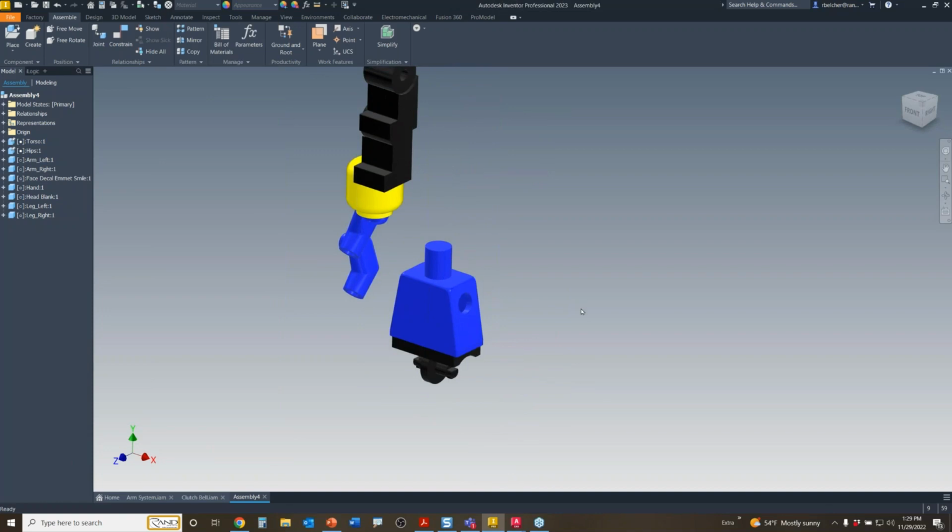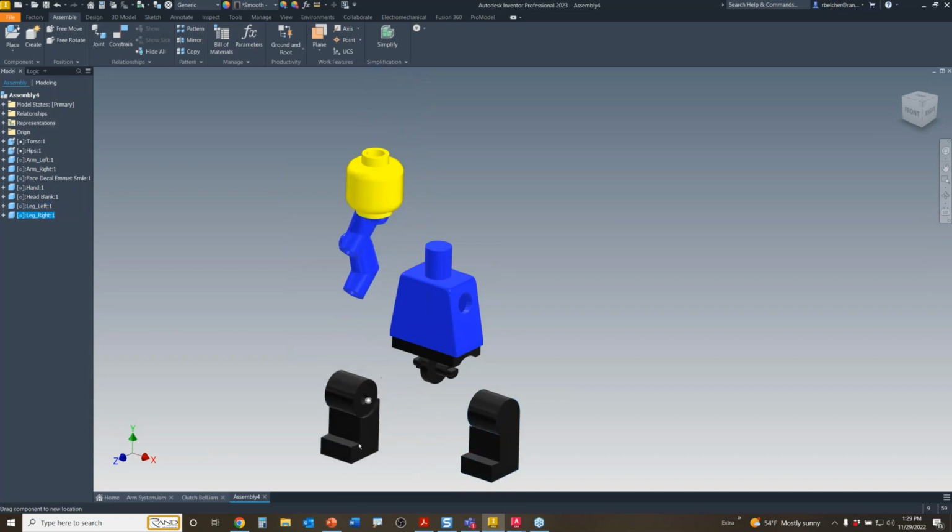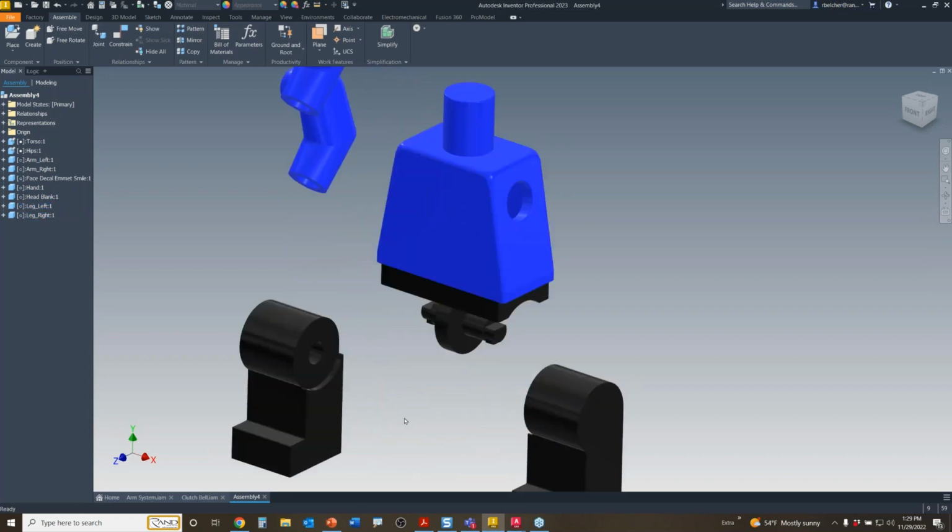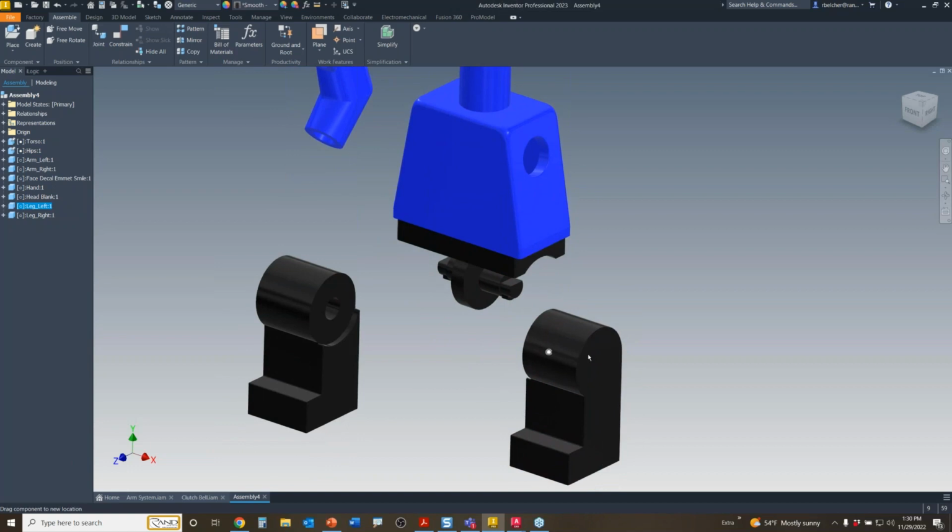All right. Now, there are a number of ways to put parts together, and I'm going to share with you something I can do with the mate constraint. It works very well with the mate constraint, but it's perfect for the insert constraints. If you need an insert constraint, you just pick circular edges. That's all you pick.